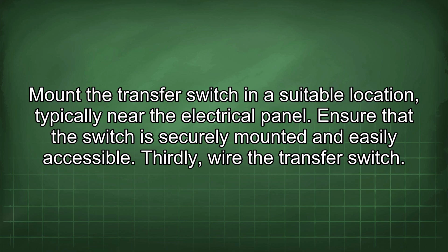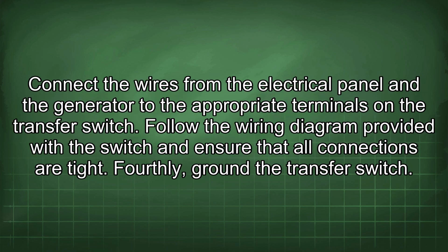Thirdly, wire the transfer switch. Connect the wires from the electrical panel and the generator to the appropriate terminals on the transfer switch. Follow the wiring diagram provided with the switch and ensure that all connections are tight. Fourthly, ground the transfer switch.